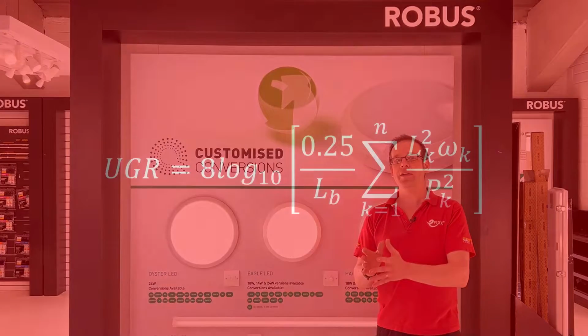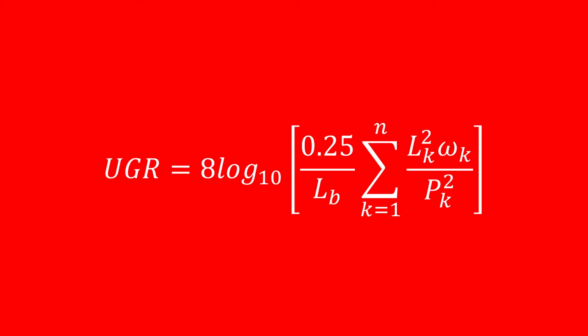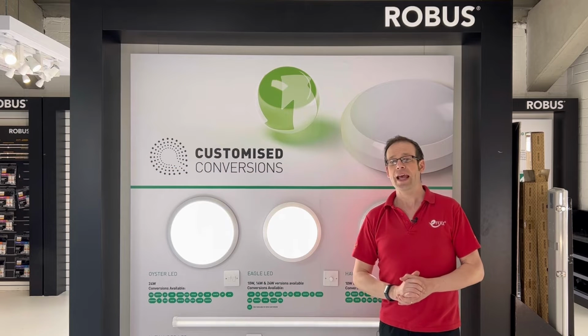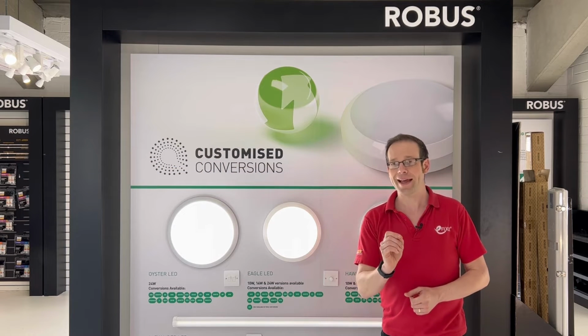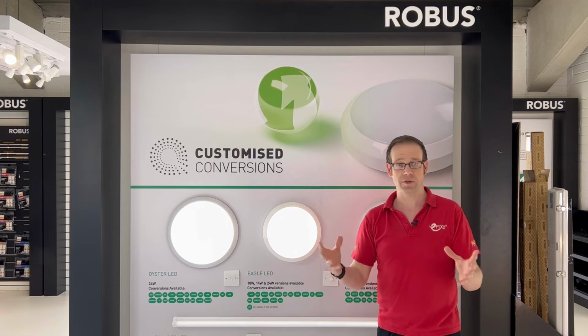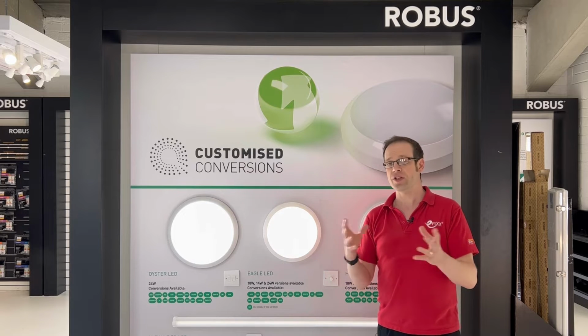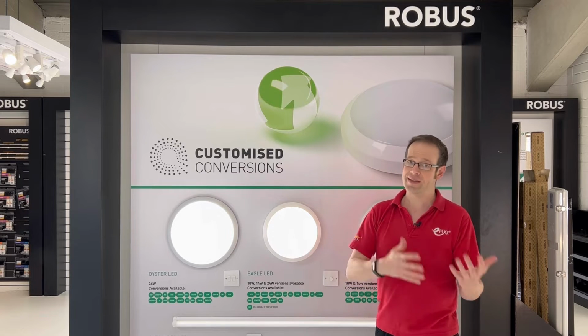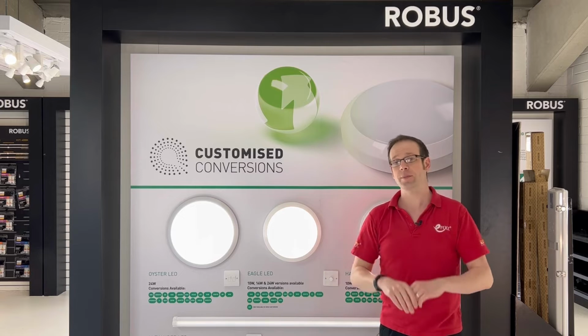In a lighting installation, glare can be calculated using this formula. Now, don't panic, you don't actually need to understand this because there's software available that will do it for you. However, you can only calculate glare at any given point in a room. You can't calculate it for the room as a total. This is because it will change depending on the perspective of someone occupying the room, where they are, if they're sitting or standing, even where their eyes are pointing.